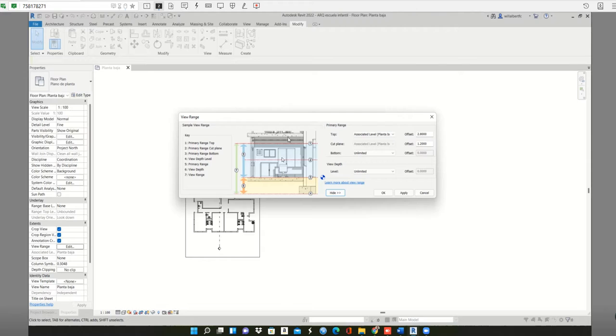The range bottom is where we can see complete elements, and in this depth range some elements are shown and some others are not. Furnitures are not shown. You will only see elements like concrete, like floors and walls. If you want to see, for example, a pipe, you won't be able to see it here. You will only see a pipe from this point up. So it's very important to know that. I will explain this later, I just wanted to mention.